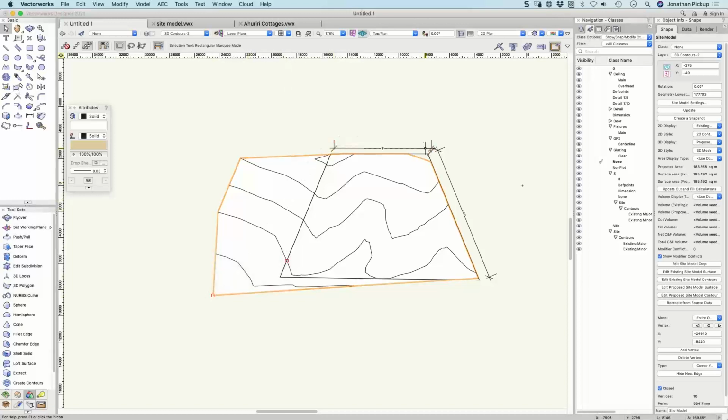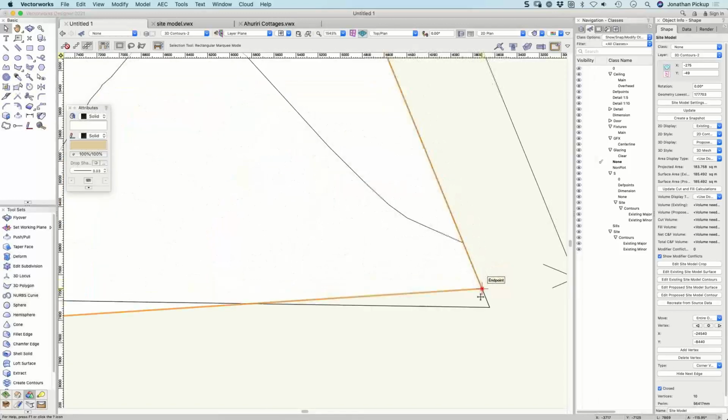So for example, you can see that my source data starts here. That was the end of my contour. It goes to that point, that was a contour, goes to the edge here, that was the edge of a stake object, that was the edge of a stake object there, another stake object there, and my 3D locus was out here. And you'll notice that this corner, my site model doesn't go all the way to my property because I have no data in this corner.